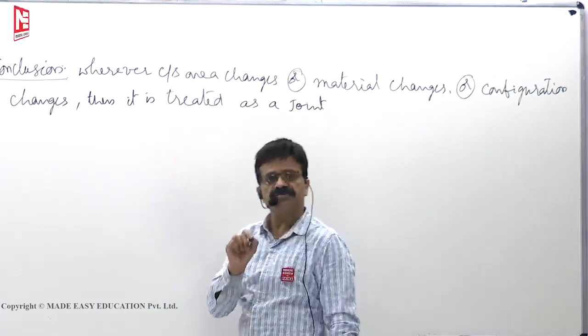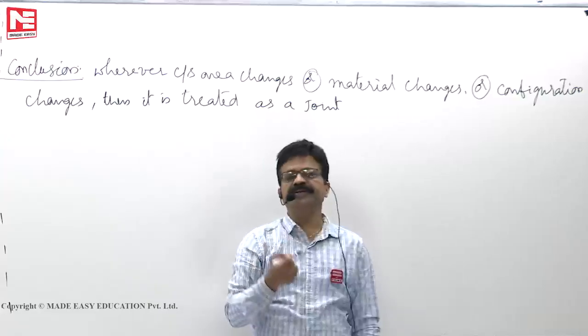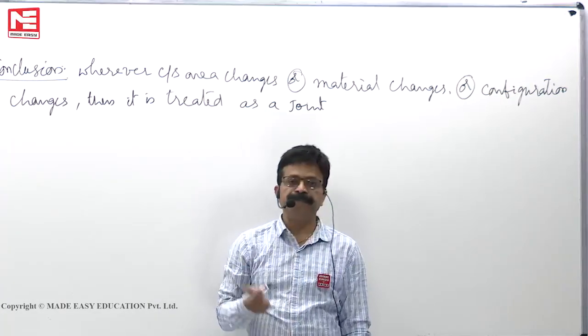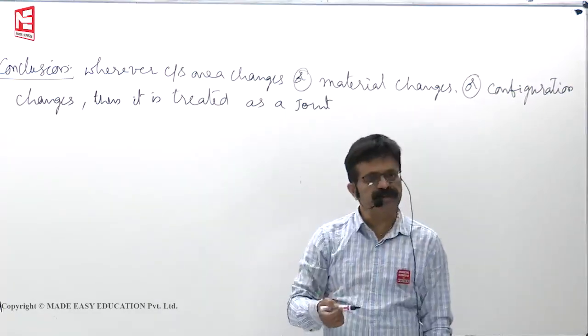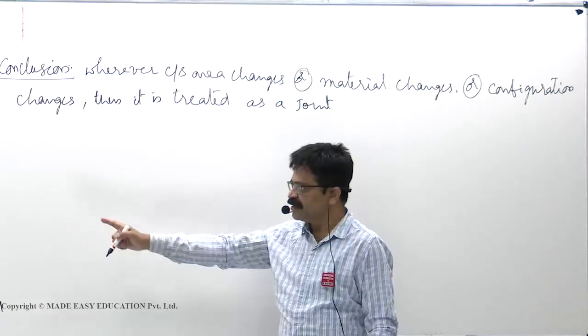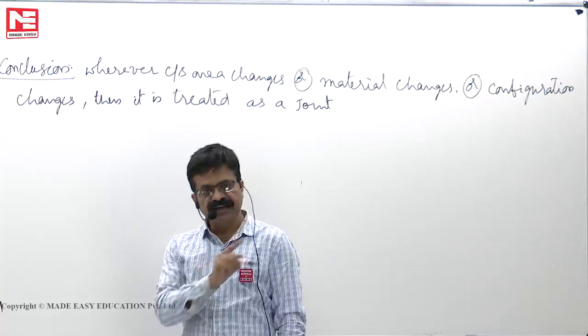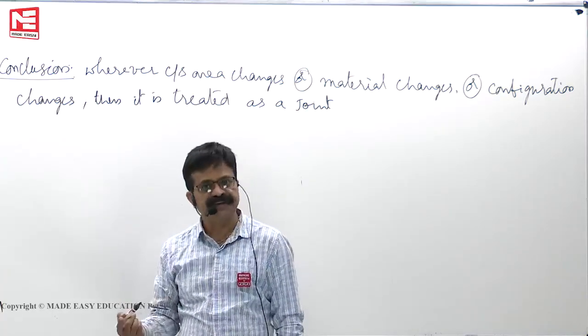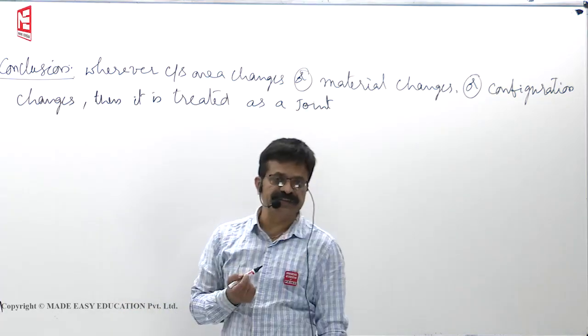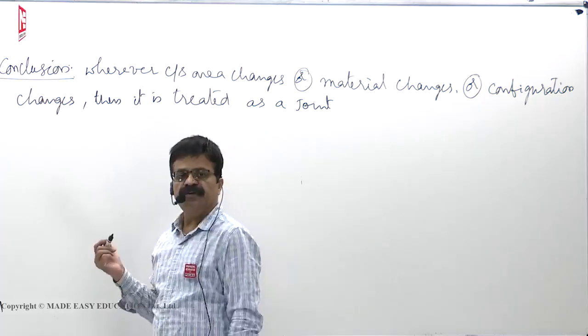That means at those joints you have to count how many independent displacements are there. That displacement can be slope or deflection. Only at the fixed beams, supposing Fy are different, at 3 locations only you have to see. Intermediate locations we can define with a curve, with an equation. So they are no longer unknowns.